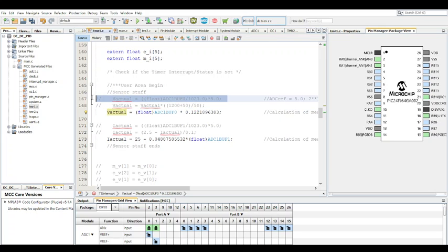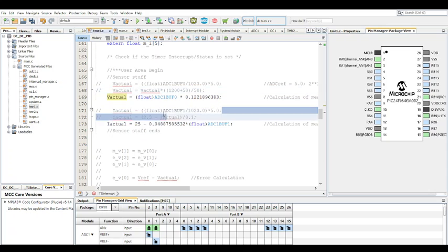Same thing as the first time: try to get the actual voltage that your microcontroller is seeing, and make the appropriate changes in terms of your ADC ref and resolution. If your ADC is 12-bit, change that accordingly. If it's not 5.0, change that accordingly.